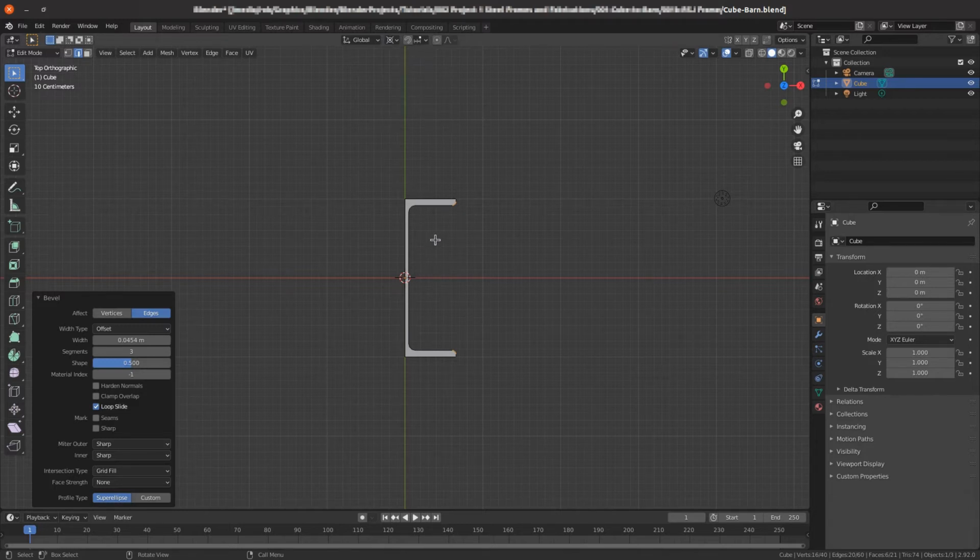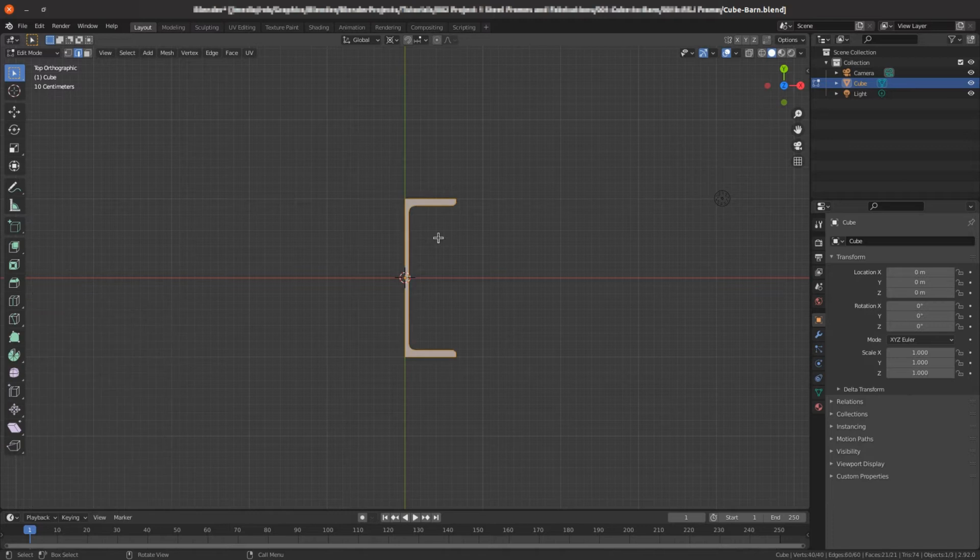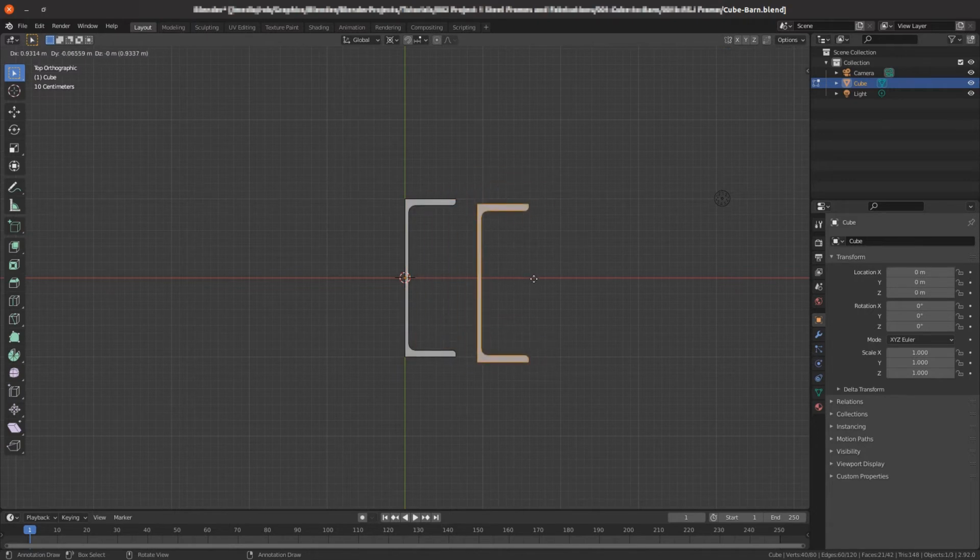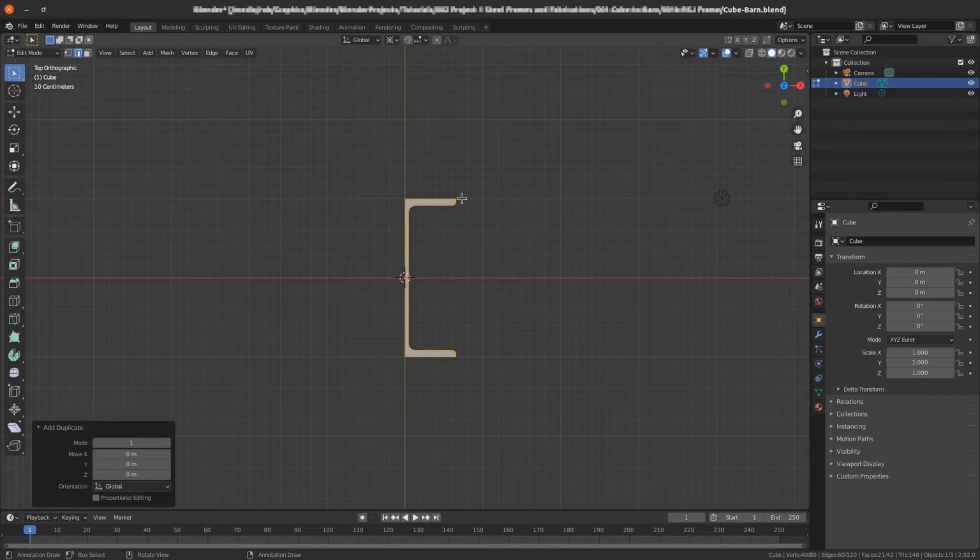And what this allows us to do is select all the vertices, so select everything and then copy them. So to copy an object, we duplicate it in Blender, so you use the shortcut Shift D, and that gives you a second version. But before you click anything, press escape, and it sits over the top of the original